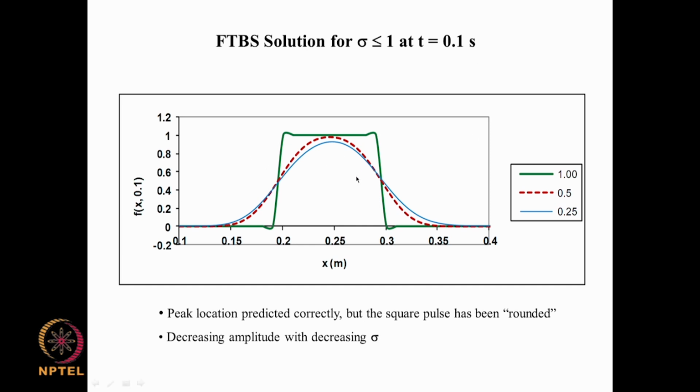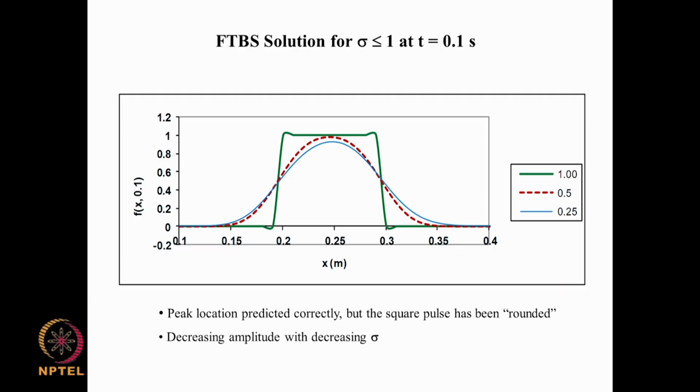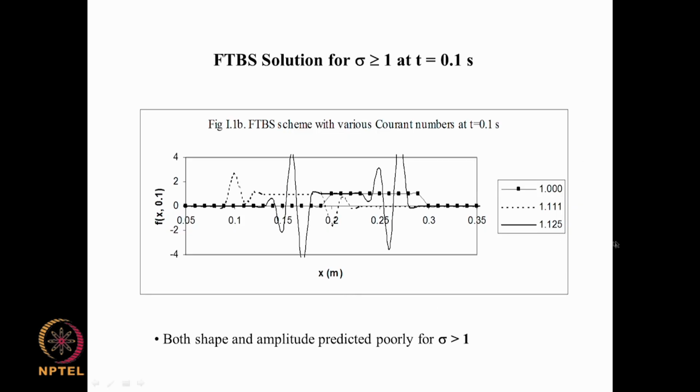If you were to increase the Courant number, we are expecting, probably because of larger discretization error as Δt increases, a slightly worse result than what we would be getting with a certain value of Courant number. And we are finding that when the Courant number goes beyond a certain limit, it seems to be giving us very odd, unacceptable, unstable results.